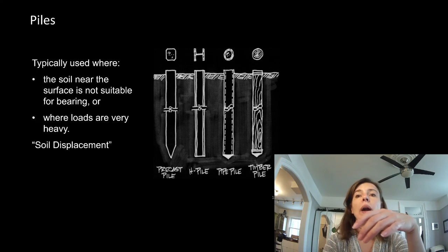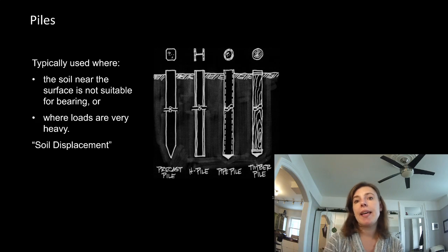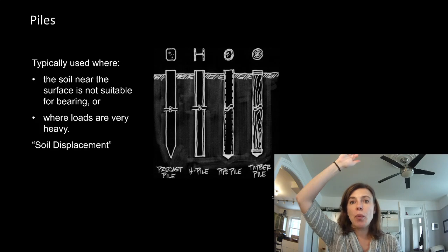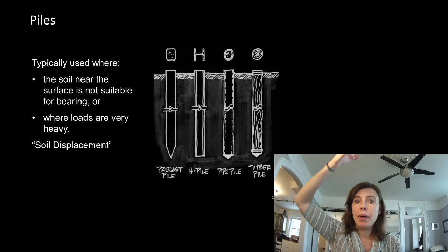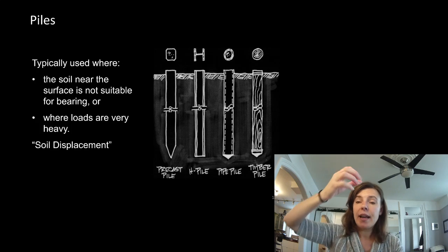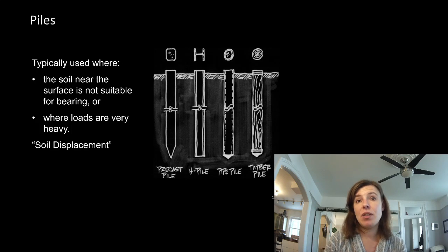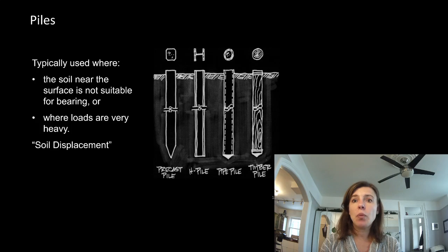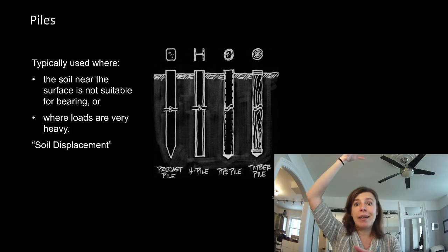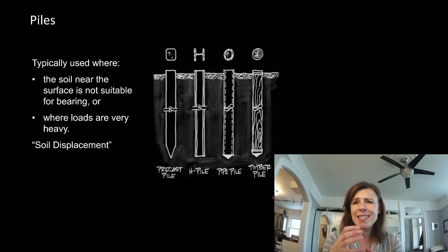Piles. Piles are where we actually drive something into the soil. We'll start with a length of it, and we'll drop a heavy weight on it and hammer it like a nail into the soil. Often, since we're worried about that thing buckling before it's in the soil, once it's in the soil, it's not going to buckle because it's being braced by the soil.